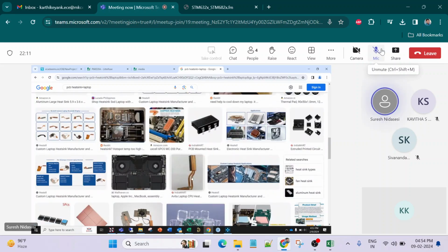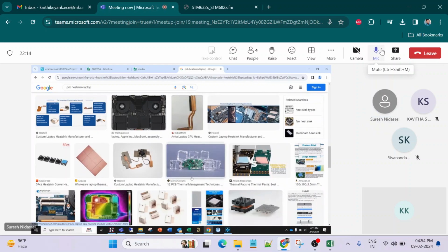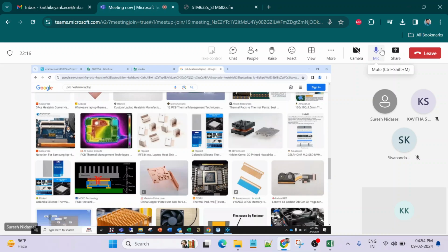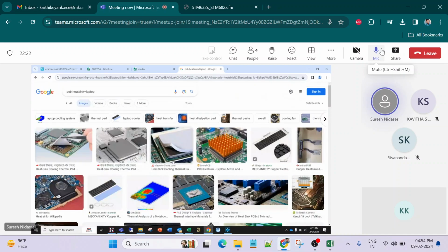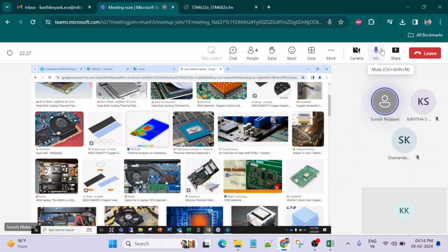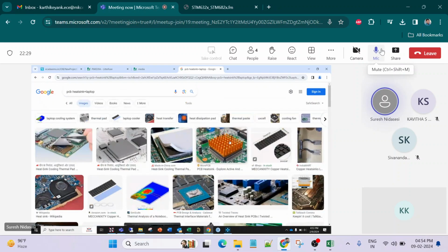Yeah, this again is a heat pipe. Sir, the heat sink is always placed over the component or on the back side of the board. Yeah, that also is possible if it's a through hole, no? Yes, sir. There are cases where it can be placed on the bottom side also. Okay. See, in one of the things we saw, but predominantly it will be above the component.